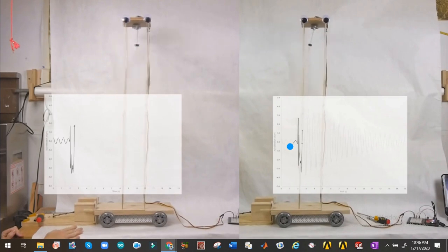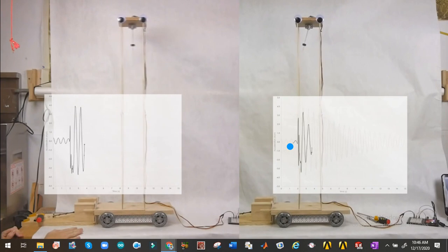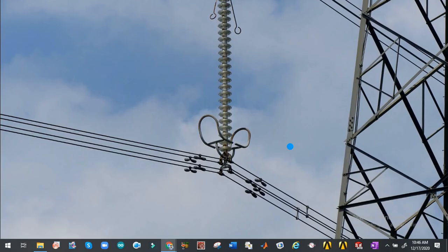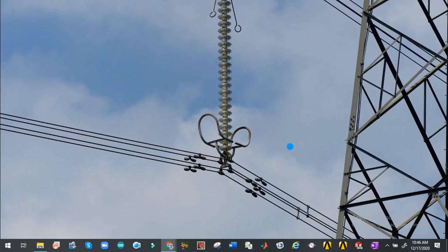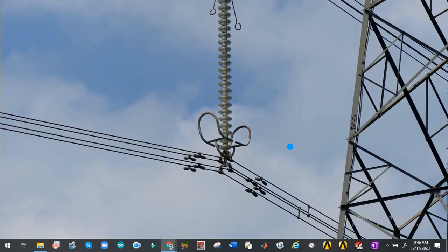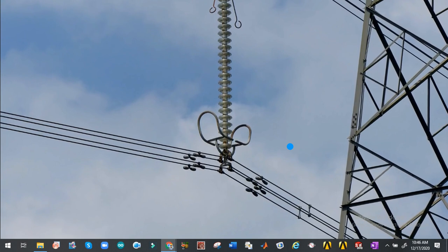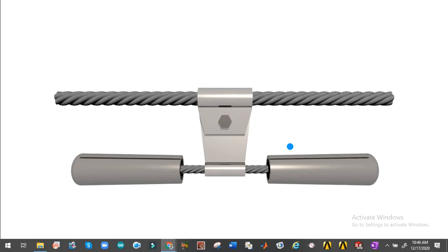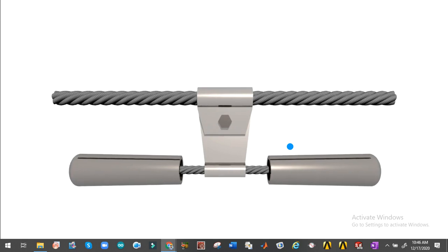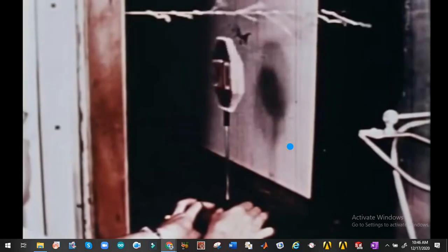Of course, bridges aren't the only civil structures affected by the wind. Take a look at the very first Practical Engineering video about tuned mass dampers to learn about how wind-induced motion can be mitigated in skyscrapers. For a simpler example, take a look outside at just about any high voltage power line. You might notice small devices hanging near the insulators at each pole. These are stockbridge dampers that help suppress wind-induced vibration on long cables and signs. And of course, other types of engineers contend with flutter as well. I've heard that airplanes are designed for wind loads, but I can't confirm it.